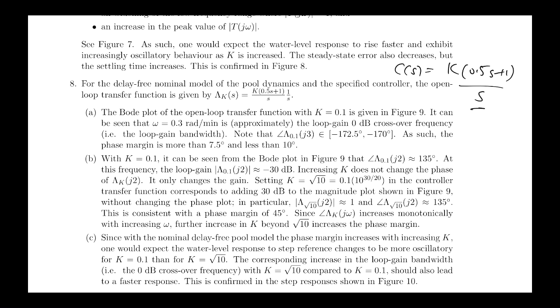Well, apart from giving you steady state error, it's going to give you new constraints on what the gain can be from the perspective of stability and performance, right? The shape of the sensitivity functions over frequency. So given that we have a pole at s equals 0 in the controller, we may not need such a high gain k to meet our steady state performance objectives, because it's being satisfied by virtue of having a pole at s equals 0 in the controller. All right? So we may not have to push up the gain so much now that we've put that in.